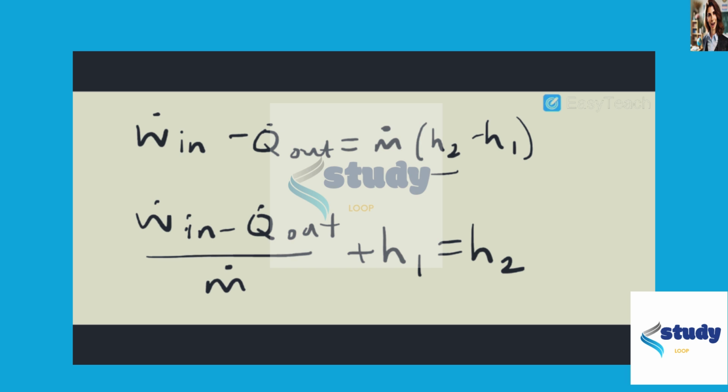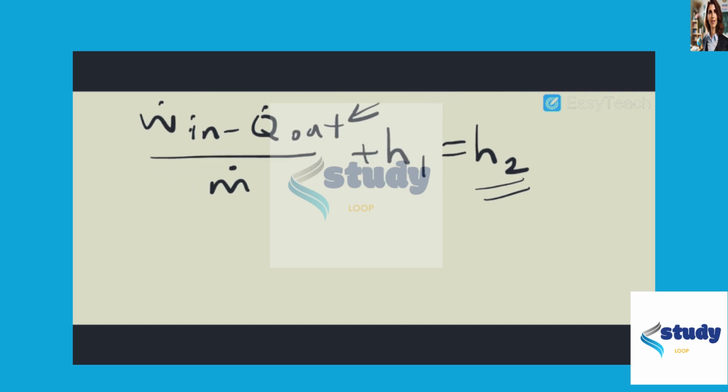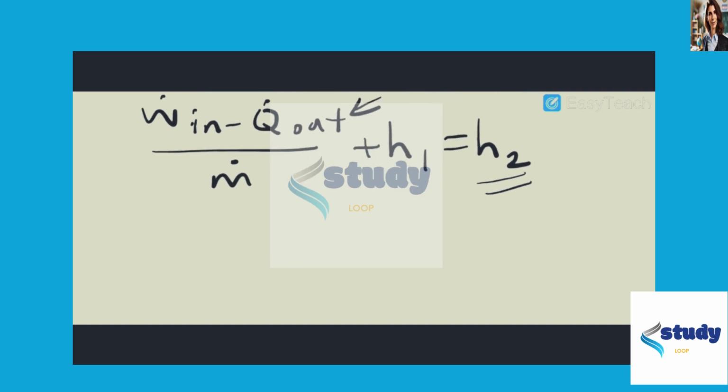Remember, we're asked to change our value of Q out, which is the heat that is being pulled out, from 0 to 100 BTU per pound mass. So what I did was change this quantity while keeping everything else constant, and that gives us values for H2. Now H2 can be directly correlated to a temperature, and what I did was compare these H2 values with temperatures in the table 8-17E, and found a list of temperatures that these enthalpies corresponded to.